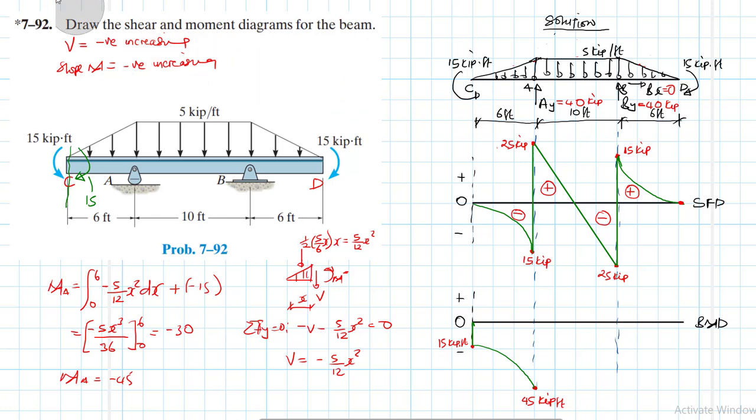Let me write down. So we have shear. Shear is positive and decreasing. Therefore, the slope for moment is going to be positive and decreasing, right? Okay. So this value there, this is half the length. So we can calculate this, and then this one is just going to be the moment here. It will be of degree 2. The quadratic function is positive and decreasing, so we expect it to go up. How much up? Let's calculate how much value it is.